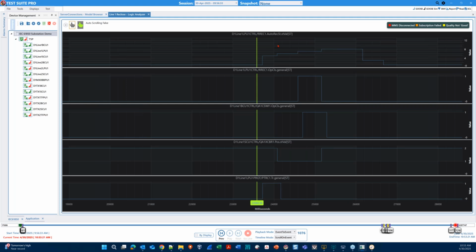To look at that from the perspective of the recloser logical node, we can step through these different states as this line steps up and down. First, before there was any fault, we were in this ready state right here on the left-hand side. Once the fault was detected, we moved up into the trip from protection state. So the PTRC right here actually issued that trip. Moving forward, a short time later, the breaker actually opened and the fault disappeared.